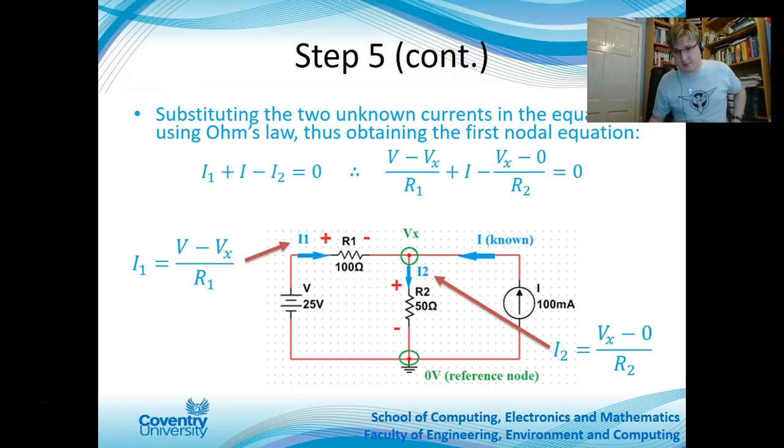I understand this might be complicated, and people might be going, oh my god, I can't do this. It's just the same as mesh analysis. With mesh analysis, you're using the voltage law and putting things in terms of currents like I1, I2. Here, you're using the current law and you're putting things in terms of voltage drops instead of currents. So it's the same process, essentially, you're just using the other law, okay?